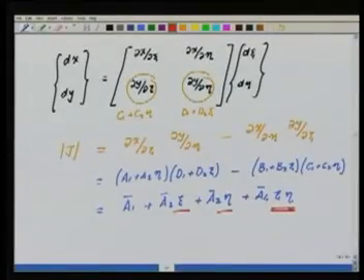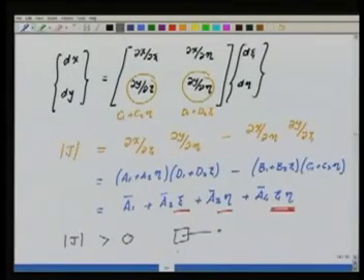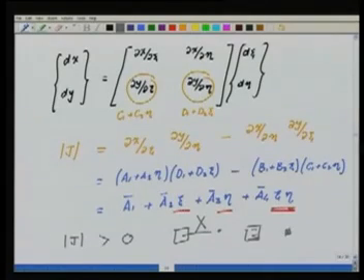The Jacobian is also a bilinear in terms of psi and eta, and we would like the Jacobian to always be greater than 0, because that's what's physical: a positive area maps to a positive area. The area cannot become negative, or map to a point, which is not allowed. An area will map to another area, and the ratio will be a positive number, maybe less than 1, maybe greater than 1. The ratio of the two areas is nothing but the Jacobian.